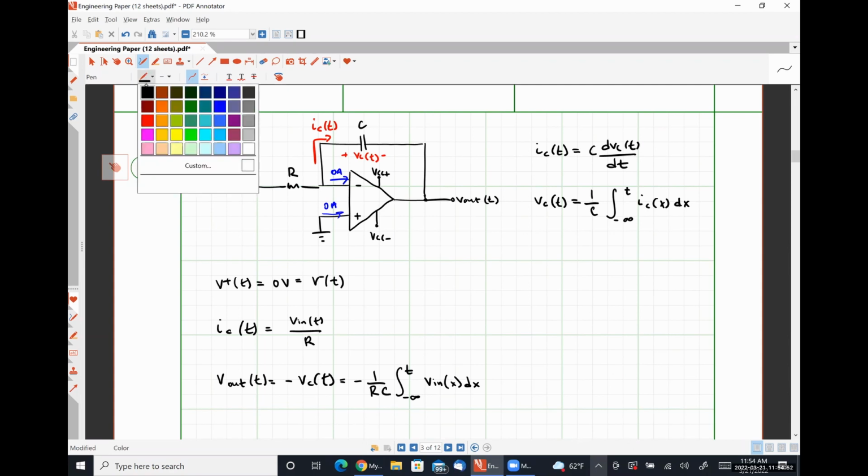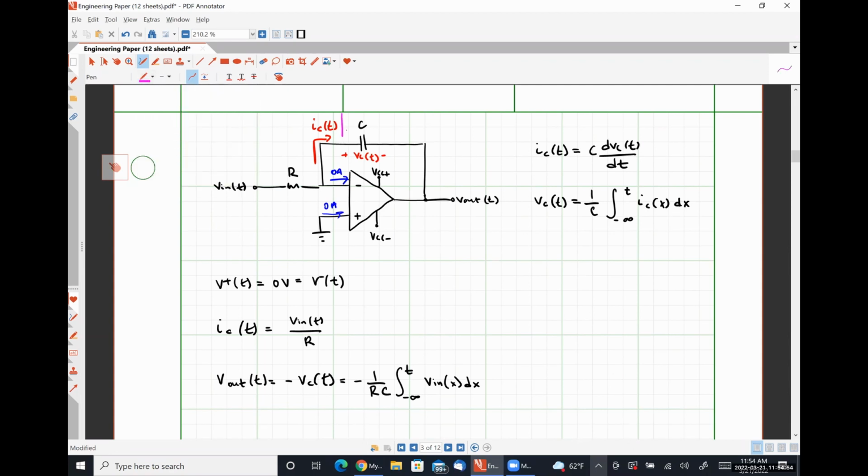How that's typically satisfied so that we don't actually have to measure capacitor voltage is by placing a very large resistor in parallel with capacitor C. Effectively, what that very large resistor does is give the capacitor a means by which to convert any stored energy into heat so that this guy always starts with an initial voltage of 0.